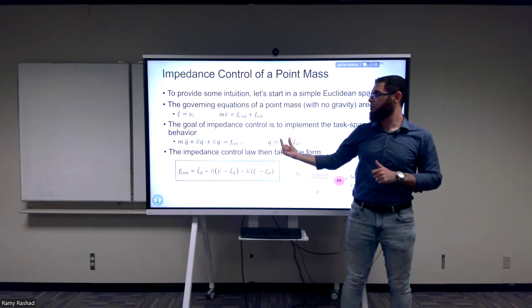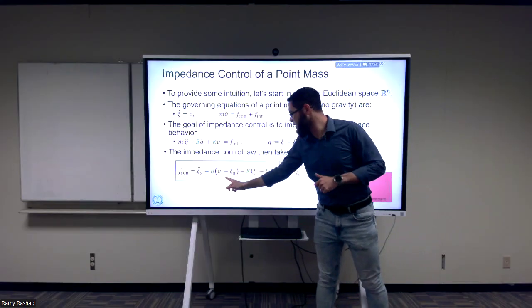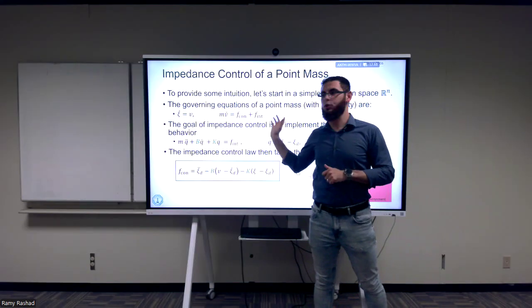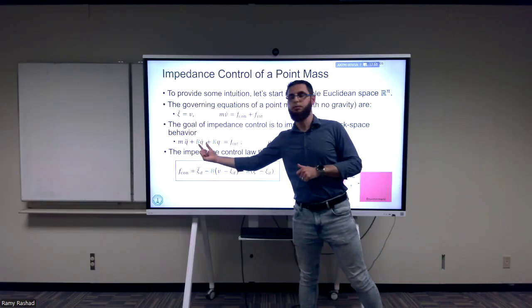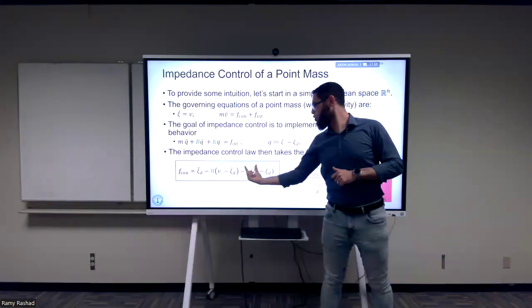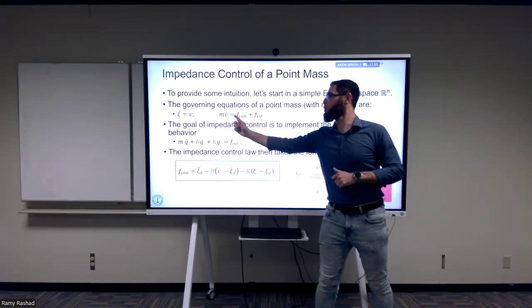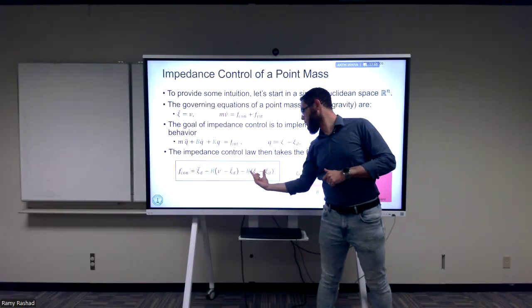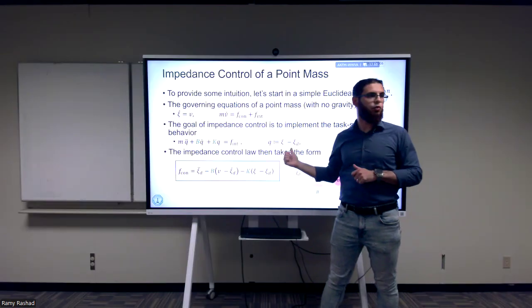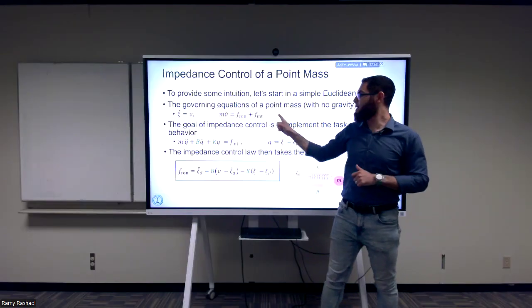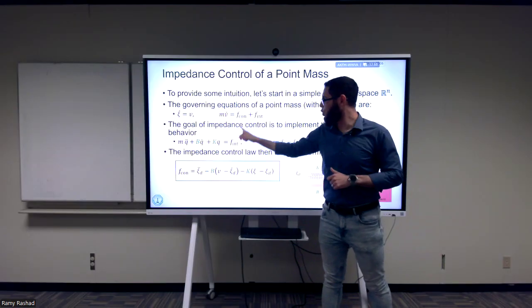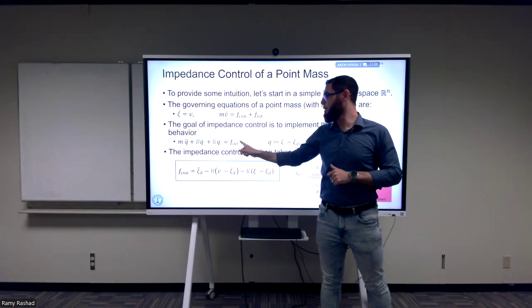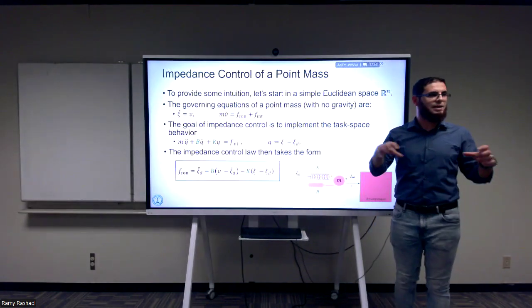So that's the first thing. When I have here minus b v minus psi desired dot, I put it to the other side, it becomes b q dot. When I choose this to be minus k psi minus psi desired, and I put it on the other side, it becomes k psi minus psi desired, which is the q. So in the end, just plugging this controller in this equation will lead to this closed loop system behavior, this impedance controller.